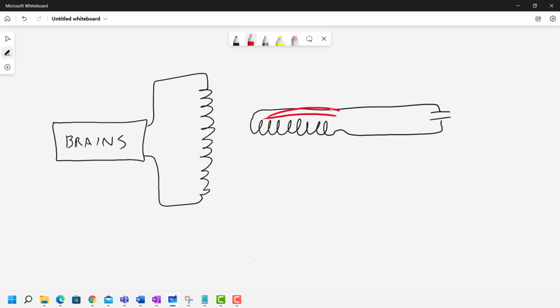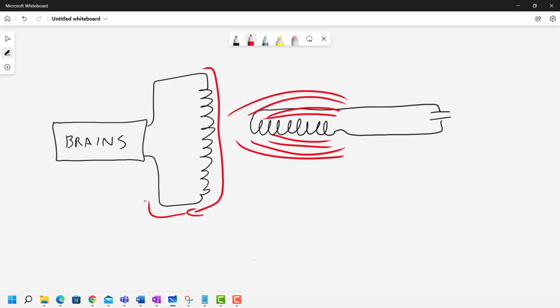Now when the brain is listening, as the magnetic field starts developing around the pen's inductor, it's going to create a charge that moves here in the tablet. And so this charge is going to be detected by the brains of the tablet. So back and forth, many times a second, the tablet is sending some current to power the pen and then listening for the resonance of the pen. Okay, and that's why the LC circuit is so important here.